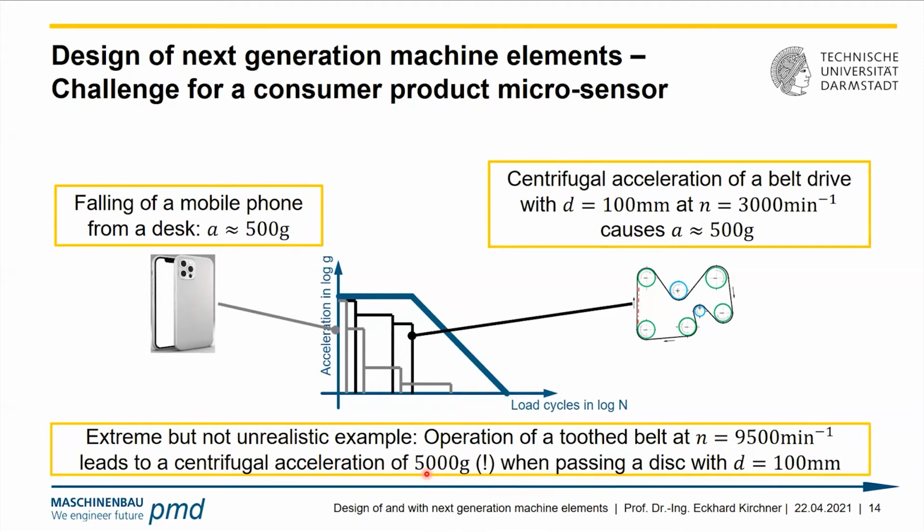loading conditions. Knowing that an acceleration sensor has a saturation threshold, typically in the area of 400, 500, or even 1000 G, we know that we have to struggle with the case that in big portions of the operational scheme, we are almost blind. As soon as the sensor passes through one of the disks, the acceleration exceeds the threshold value, and we can't read anything from that. We just go into saturation. So we have to sort out all those problems.